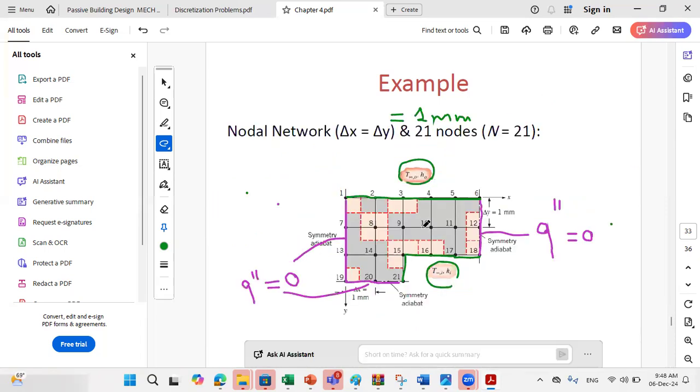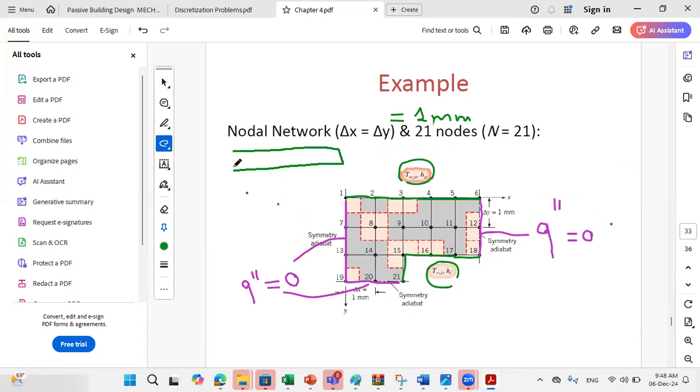The number of cells also depends on how you want to treat your extreme cells. As we know, we have two approaches. We can consider for extreme cells a size of delta x over 2 and delta y over 2. In this case, they used this approach: whenever I need to take nodes at the extremity of my domain, if you choose to do this, then you need to consider for extreme cells sizes of delta y over 2. So for a corner, you have delta y over 2 and delta x over 2. And for normal cells inside the domain, you have delta x and delta y.